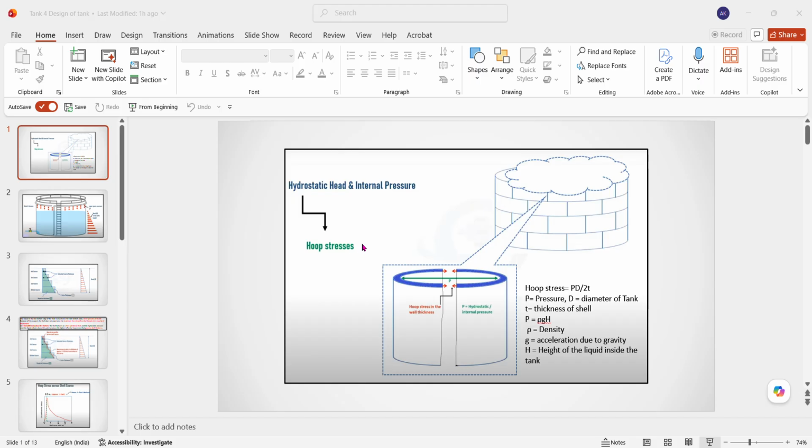If the tank diameter is less than 50 feet, then your nominal plate thickness should be 5 millimeter. If your calculation gives 3.5 millimeter, you cannot go for 4 millimeter. You have to select 5 millimeter thickness, or 3/16 inch.